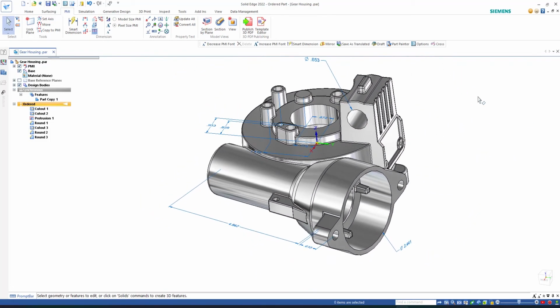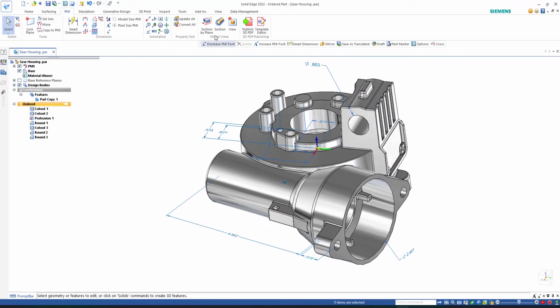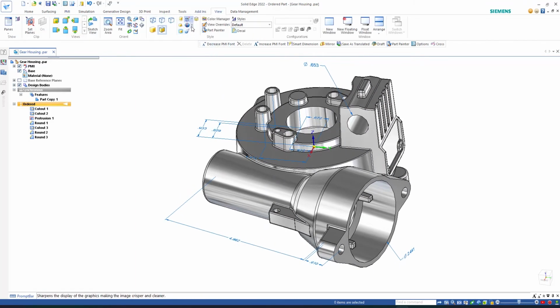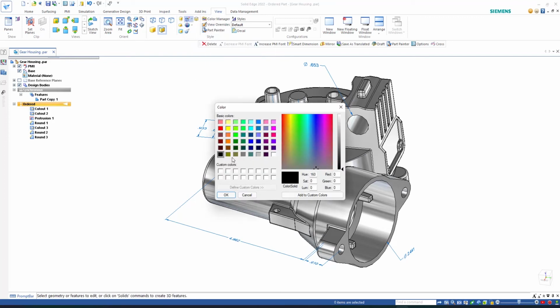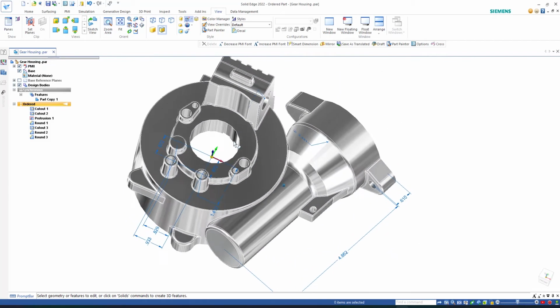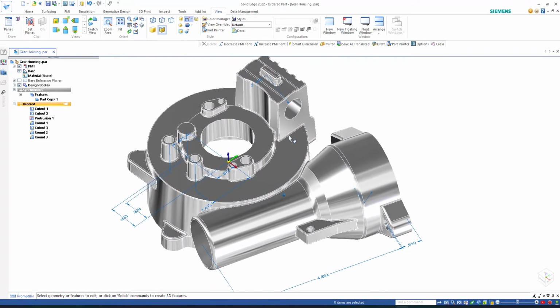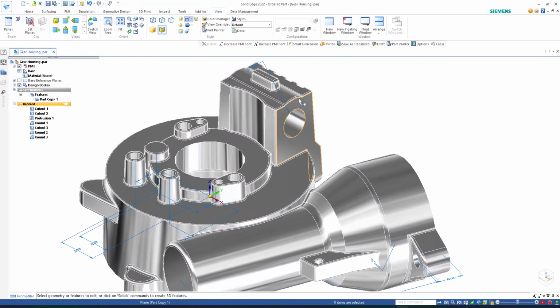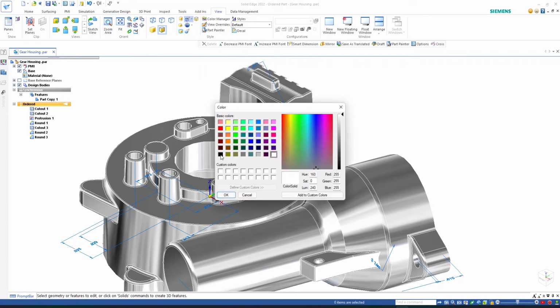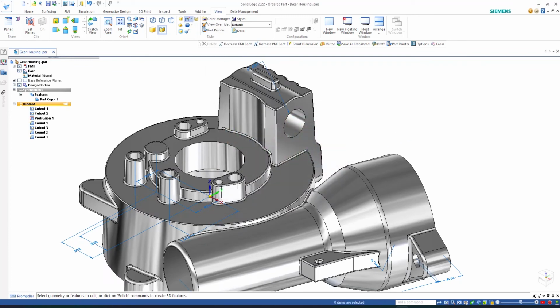The other thing is, in some cases, let me turn that on, it's called the select edge color. Sometimes you see the setting is set to white by default, and to me that makes it hard to figure out where the lines end and begin, especially on circles and things like that. So I explain to them again that there is an option: go to select edge color and always have that in black. To me, it's much clearer as to what I'm selecting there.